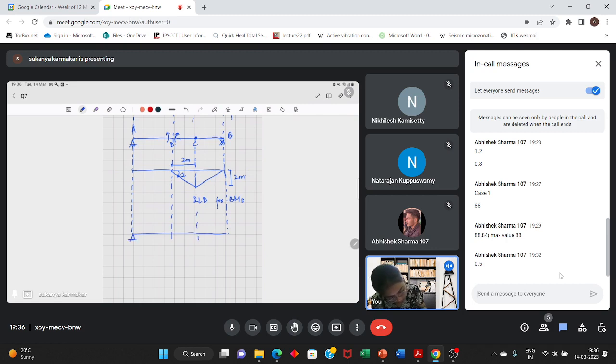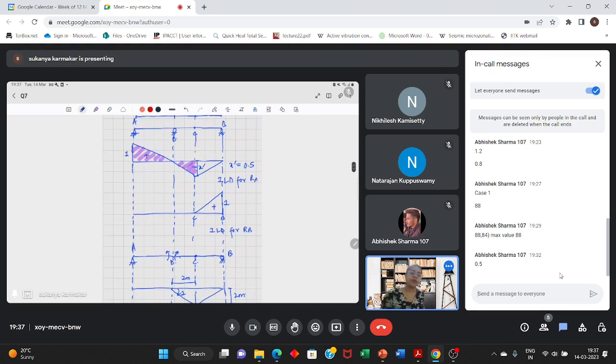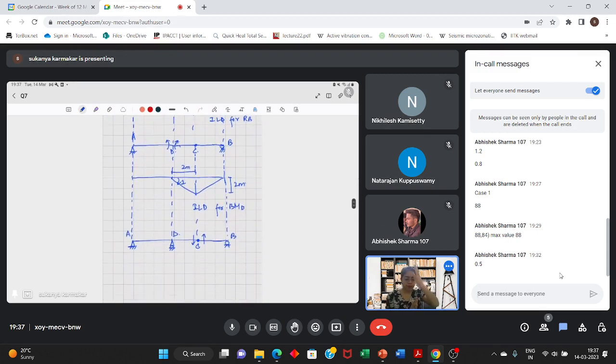Let's draw the beam once again. This is A, this is B, this is D, C. At D you have a roller. D, A, C, and C is an internal hinge. Here you are allowing sliding. So basically you can push this beam up. Now, without breaking the portion A, C, D, can you push up the joint C and maintain zero?